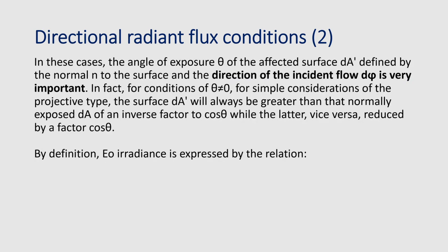Alright, in these cases, the angle of exposure theta of the affected surface dA1 is defined by the normal n to the surface and the direction of the incident flux, d phi, and is very important. In fact, for conditions in which theta is different from 0, for simple consideration of the projective type, the surface dA1 will always be greater than the normally exposed dA by an inverse factor of cosine theta; vice versa, it is reduced by the factor cosine theta.